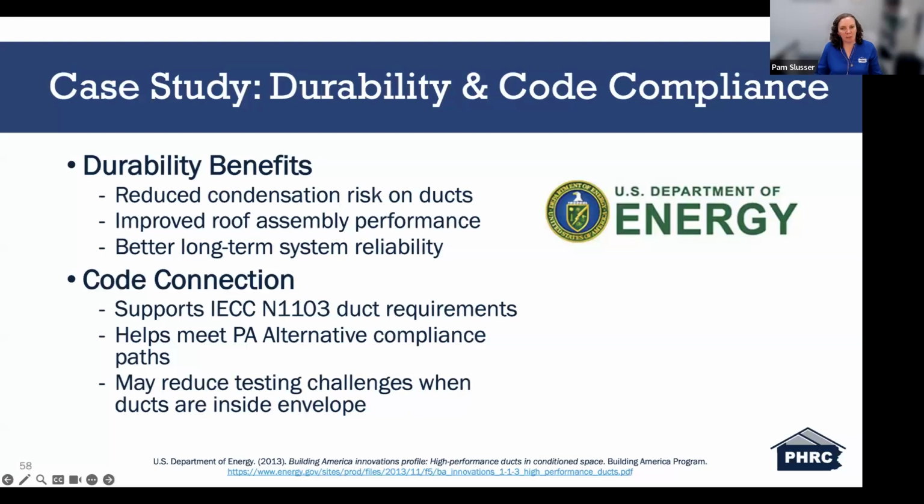From a code perspective, this approach aligns well with the code requirements, particularly under the N1103 for duct systems. It can also support Pennsylvania alternative compliance paths and in some cases simplify and reduce duct leakage testing requirements when the system is fully inside that envelope. So overall, this case study reinforces that duct location is a critical design decision, one that impacts not just efficiency, but comfort, durability, and code compliance as well.